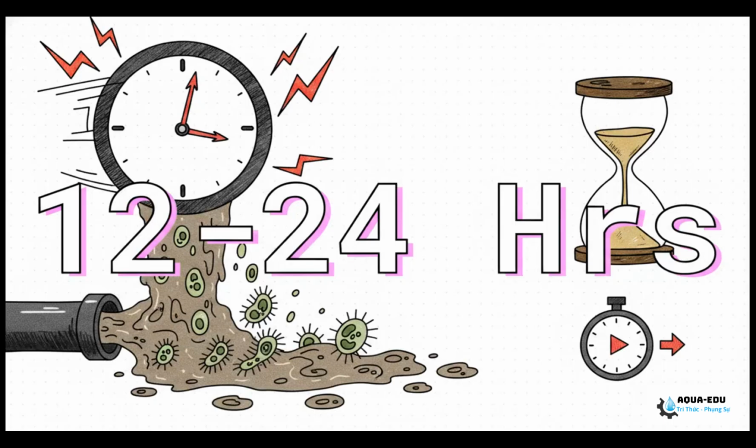Now, here is what is truly terrifying. The time frame. I need to warn you right now, once FOG hits over 100 milligrams per liter, you only have 12 to 24 hours. That's it. Just 12 to 24 hours before the entire biological system is completely paralyzed. The clock is ticking the absolute second that grease enters the headworks.